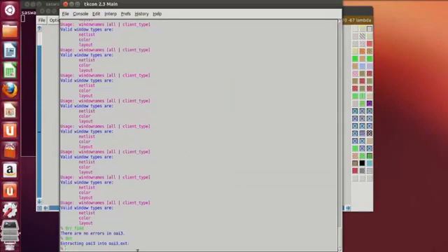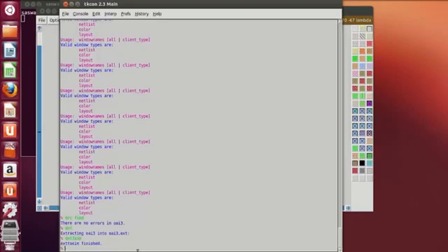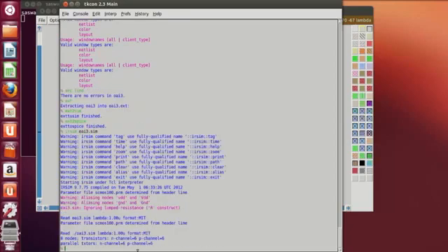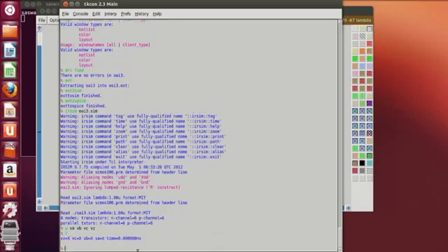Then extract. Ext file generated. Extract to sim file generated. Then extract to spice. The spice file is also generated. Now after generating the sim file, type sim oai3.sim. Keep a watch on VA, VB, VC and VZ. Press D. All the values are given as X.